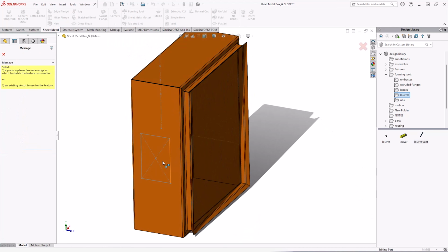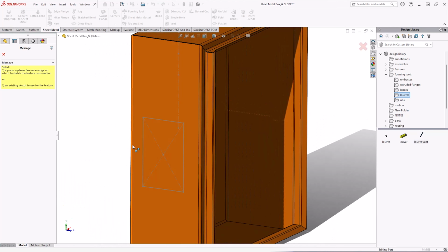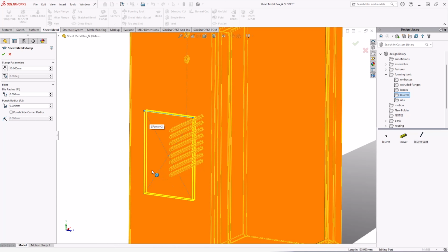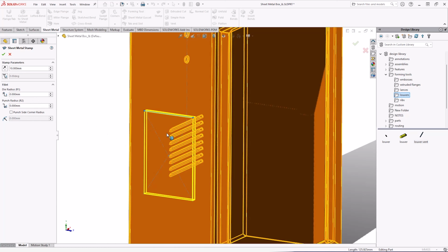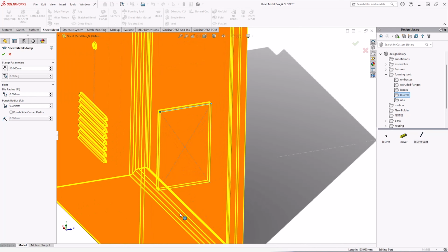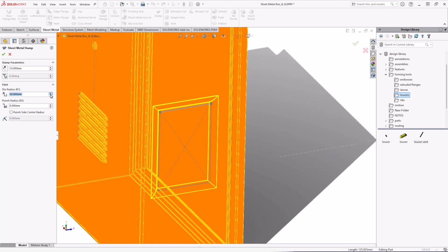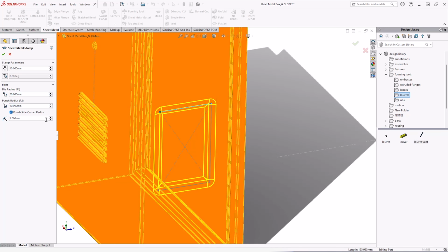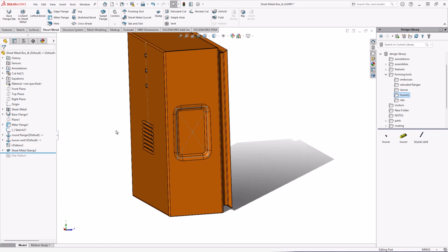You can simply drive it from a sketch. So click your sketch you want to create, and you want to drive the embossed feature from, or the stamp, and we can specify the radiuses of the inside die radius, the punch tool radius, and actually the radius of the profile as well. And that's a great indentation that we can add a label to or mount a handle to at a later point.